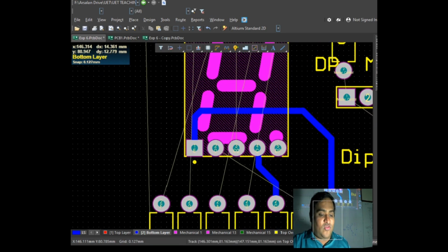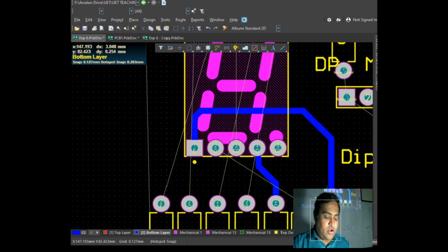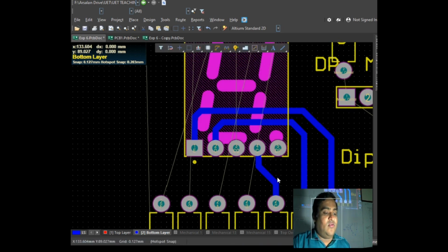Similarly, now when this is connected, this pad has to be connected with this pad. So this means very easily, again click place track or Control W. Now there is an ample space in the bottom, so I can take it back down and here, and this is connected over here like that. So now 3 tracks are done.